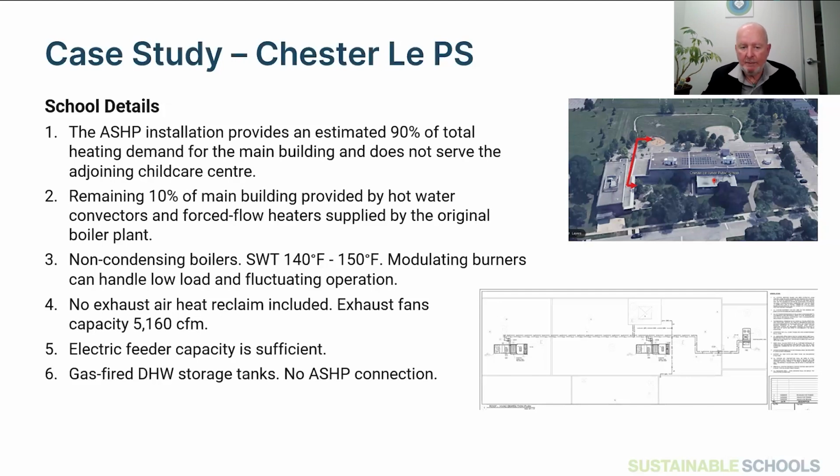The school does have a boiler plant. The boilers lend themselves to the significant load variation as the air source heat pumps come on and off. There was no exhaust air heat reclaim in this particular case. The electric feeder looked fine, and domestic hot water is not served through the air source heat pump operation.